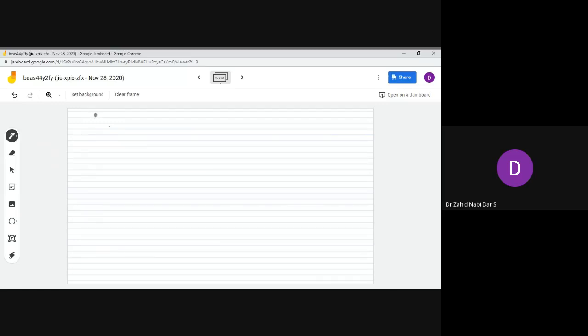So therefore the total number of slots is 36. The coil in slot 1 is connected to the coil in slot 10, because you just found the coil span to be 9 slots.